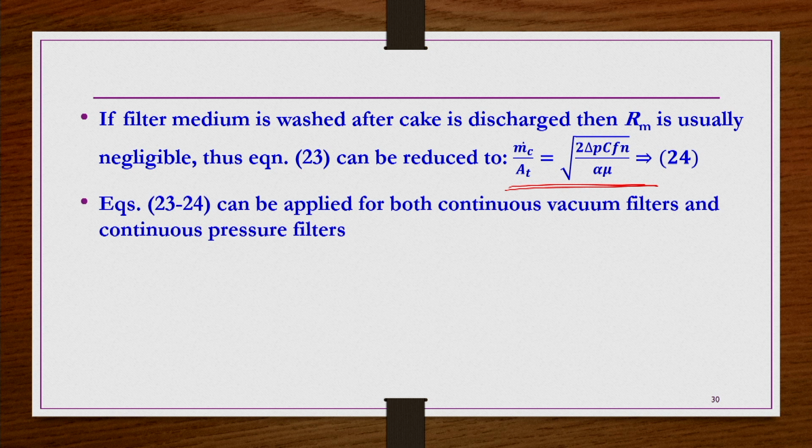So, these equations 23 and 24, this equation without Rm and the previous equation with Rm terms, can be applied for both continuous vacuum filters as well as pressure filters, though we are writing them for the pressure filter kind of thing. So, they are also valid for vacuum filters.